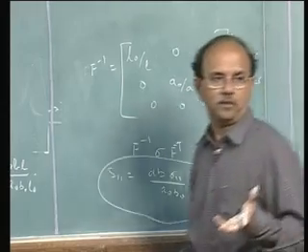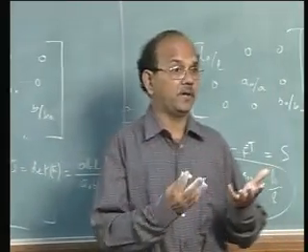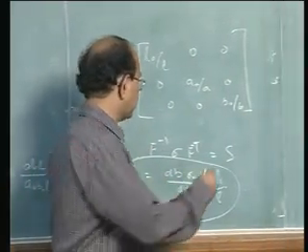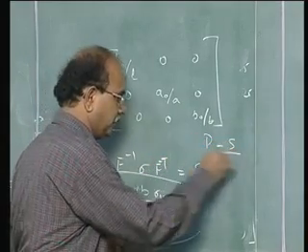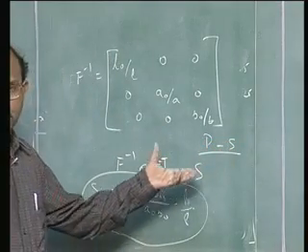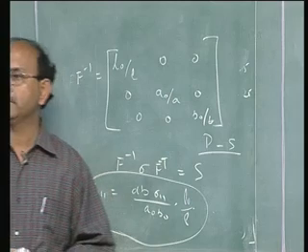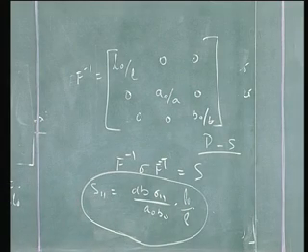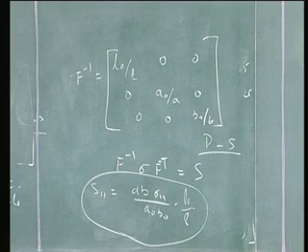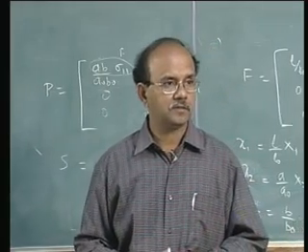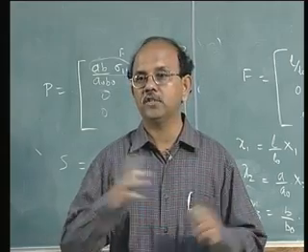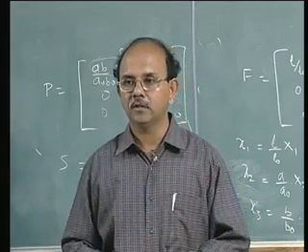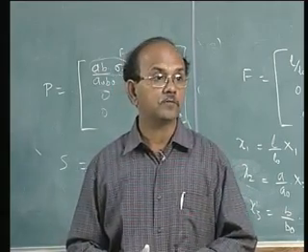Yeah, first Piola-Kirchhoff stress, right. So, you can develop a relationship between P and S. I leave it to you, it is very straightforward to develop. Please develop a relationship between P and S. But keep this in mind, and we will encounter second Piola-Kirchhoff stress quite often in the implementation levels. But if you just use it, you will not encounter second PK or second Piola-Kirchhoff stress.